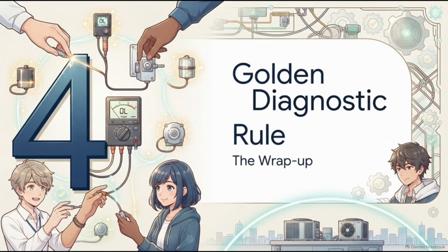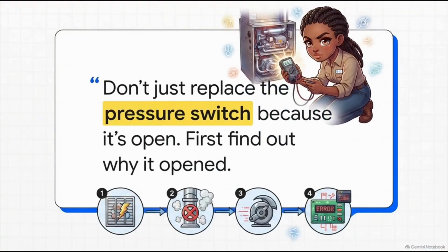Which brings us to Section 4, the Golden Diagnostic Rule, the wrap-up. I want to let this next thought really sink in, and frankly, it should become your professional mantra. Don't just replace the pressure switch because it's open. First, find out why it opened.